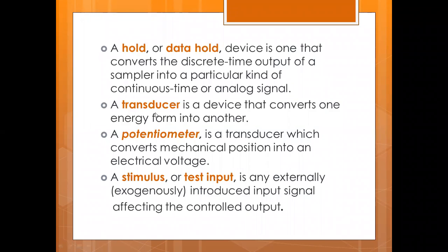Now, the transducer is a term that was already introduced to you at the start of the semester, last semester. It is a device that converts one energy form into another. So a transducer converts a signal in the form, let's say, of a physical signal into an electrical signal. So your control system cannot interpret physical signals. What it can interpret are only signals in the form of currents or voltages. So the one responsible for converting such is the transducer.